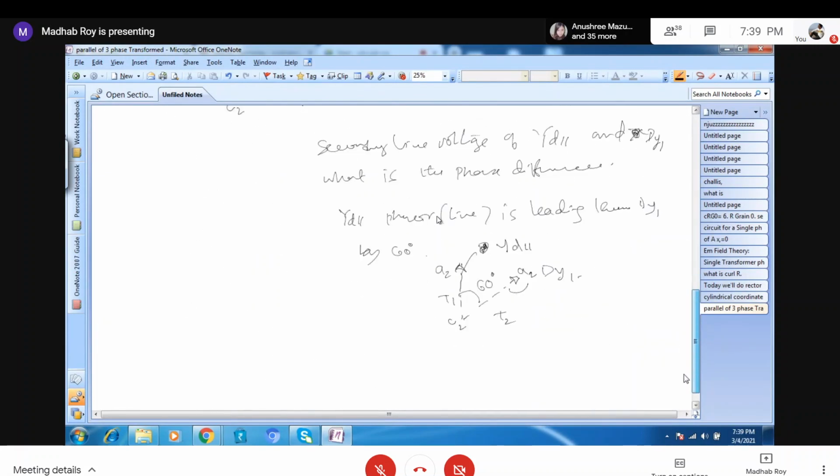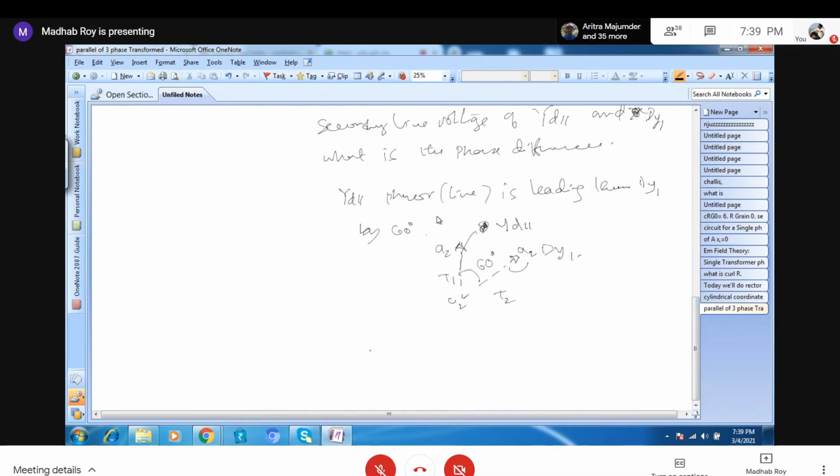So for doing parallel, we have to make this 60 degrees to 0 degrees. That is our task. Do you understand that? Yes, sir. Otherwise, we can't do the parallel operation.